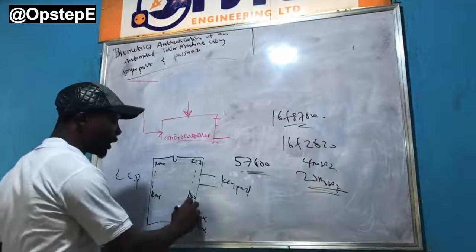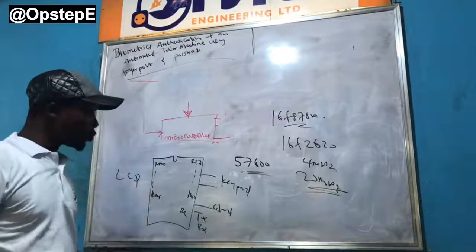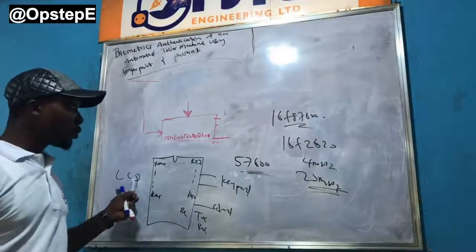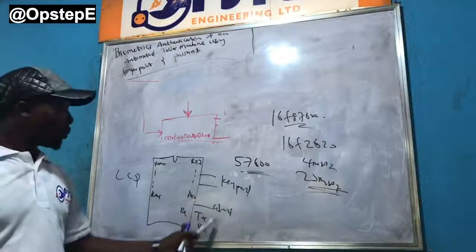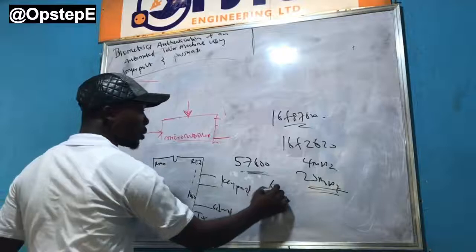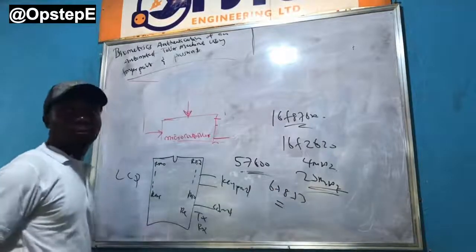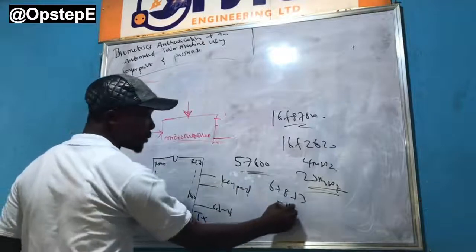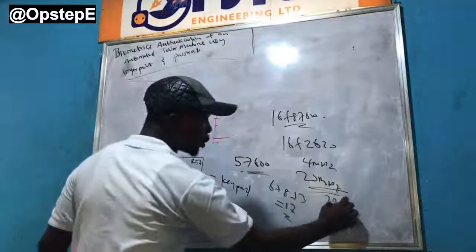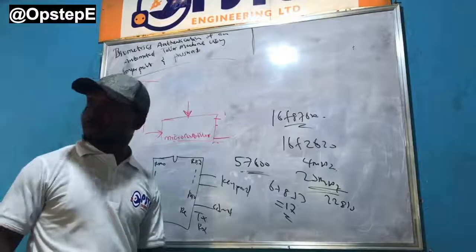And then you have one other indicator for change password indicator. So 3 was used for that. So all the pins on A will be used, all the pins on B will be used, 3 pins on C will be used. So this is 6 plus 8 plus 3. This is 9, that's 17 pins, isn't it? From the 22 mutable pins, how many are left? 5 pins were not used.